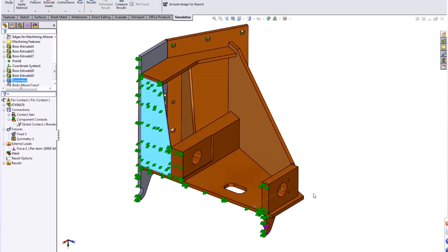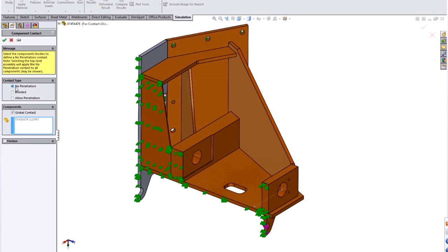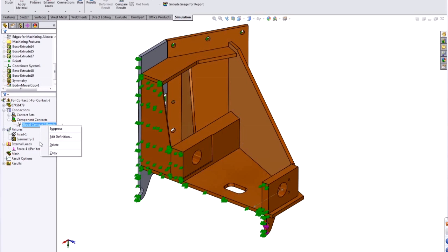Any faces that have a touching relationship, this glues them together. You can tell the software that every touching face is actually a sliding relationship, or you can delete it if you don't want any assumptions made out of the box.